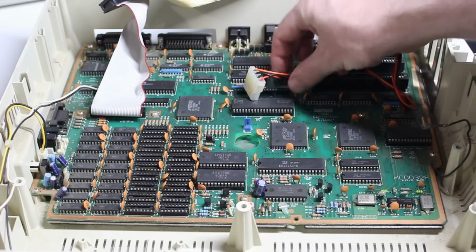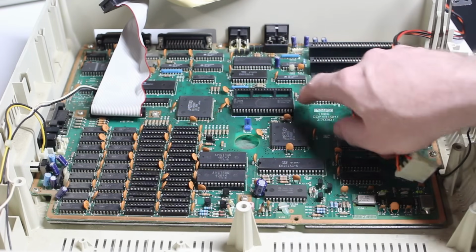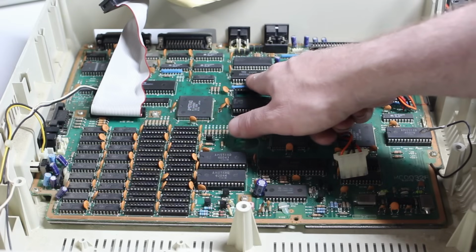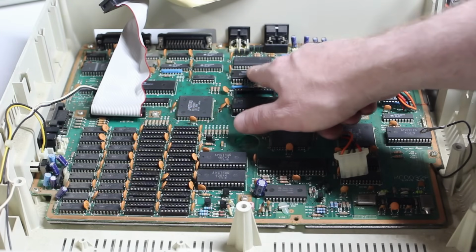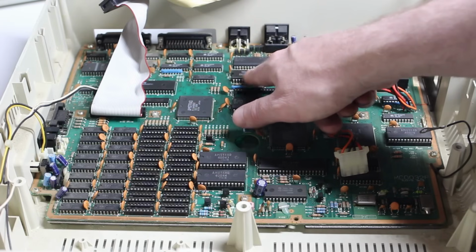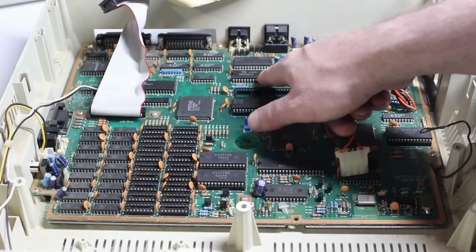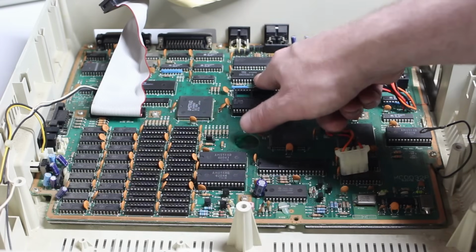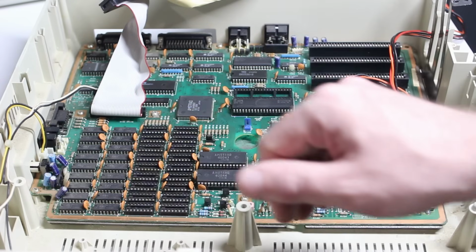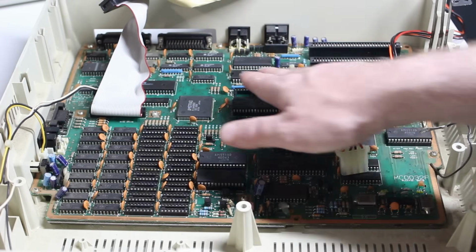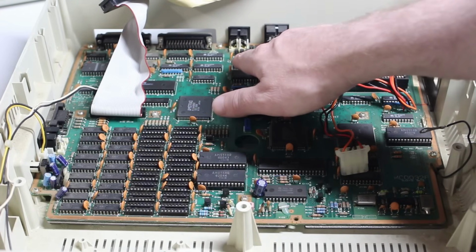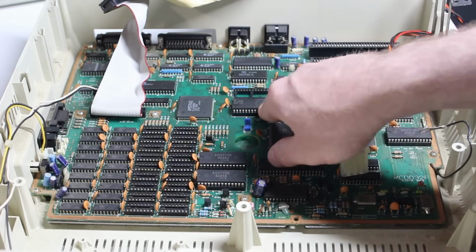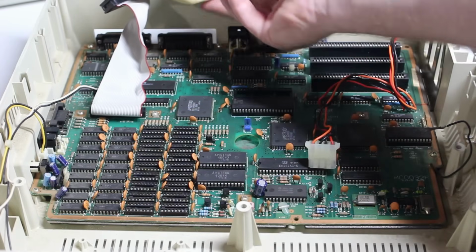Obviously there's an empty socket for an 8087-2 math coprocessor, which we don't have in this machine. And there's also an 8253 programmable interval timer, and that's used for system timer and presumably to run the speaker, and maybe also for the pulse that does the DRAM refresh. So it's probably that will be turning off when we do manual RAM refresh, and I'll talk a little bit about that later on. This is an 8259 programmable interrupt controller, and it's just a chip that you need alongside the 8086 to handle interrupts.